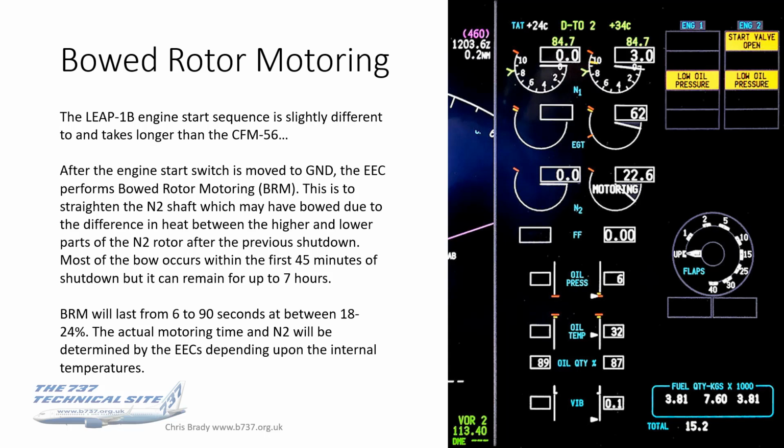First flight of the day, you can probably get one lit in about 90 seconds from cold. So not that much different, but if you've only landed within the last hour and you go to start it up again, it'll take 3 minutes per engine, and meanwhile you've got a queue of traffic behind you at the airport.